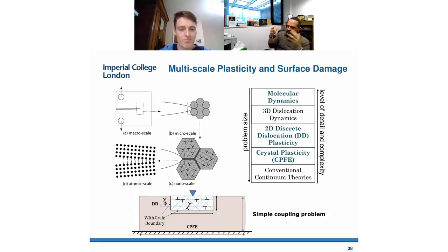Taking an example from a different field, fracture mechanics, everybody knows that in order to understand how a crack develops, you can look at it at different scales. You can look at the grain scale, at the dislocation motion level, and at the atomistics of bonding. The same can be applied to tribology. If you take a nano-indenter, the indentation between a tip and a material will be governed by the interaction of a single asperity, all the way down to the interaction between the dislocations under the indenter and the grain.